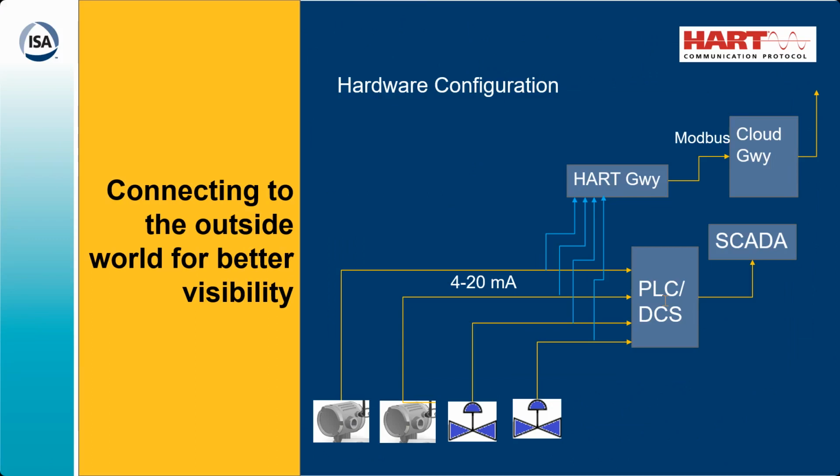For wired HART, you are working in a query-response format where, suppose you have 4 devices connected, you are getting the data every 500 or 750 milliseconds, at a predictable latency.